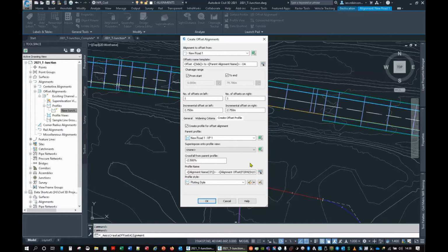So what that does mean is if we're going to have a single crossfall on this road and you wanted to use this method, just simply set 0 on there and put it at the crossfall you want, and then repeat command and set 0 on that side, and then do your crossfall on the opposite. So it can be done, but we'll just go with that.